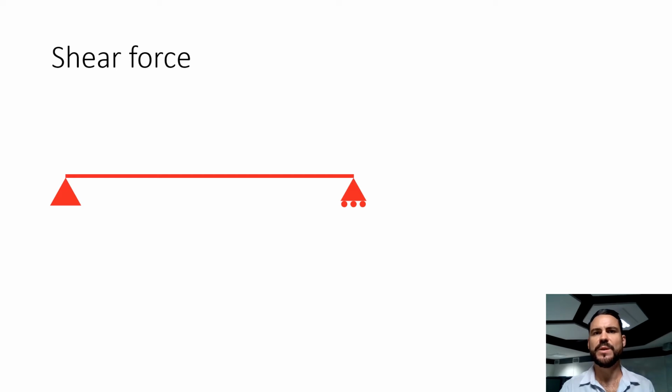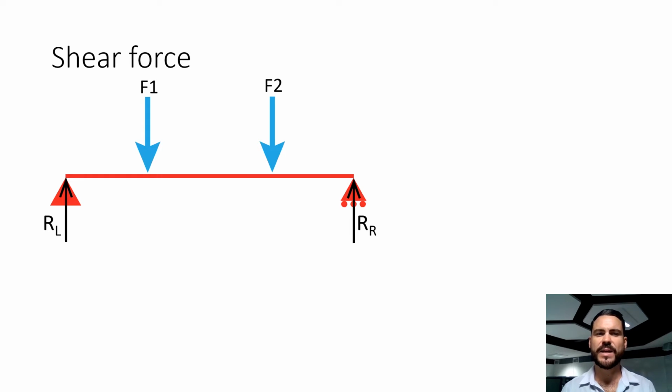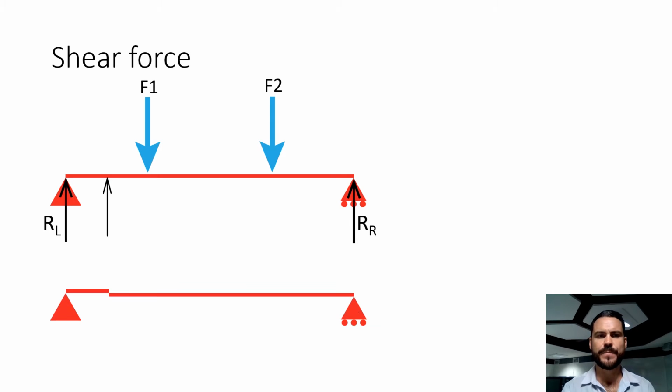What shear force is talking about is when we've got forces acting on the member, just like our diagram suggested, and we've got our reactions, right and left, you then hopefully start to gain a little bit of an understanding of Isaac Newton's third law. For every action, there is an equal and opposite reaction. So when we've got a force pointing up and we've got a force pointing down, and notice that those actions are slightly offset from each other, we need to ask ourselves what's occurring in this space here, okay?